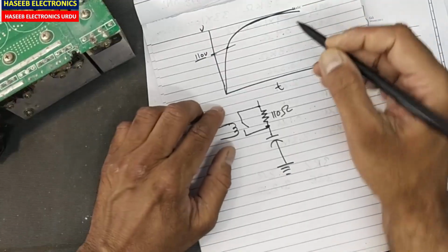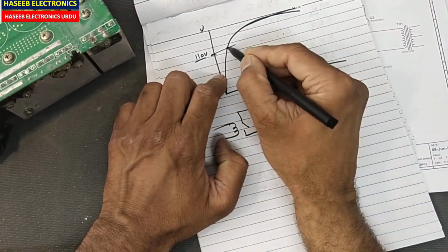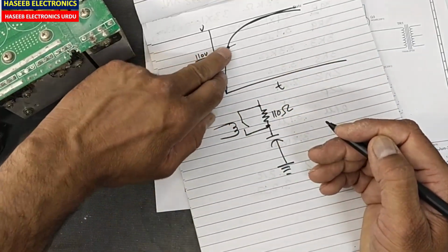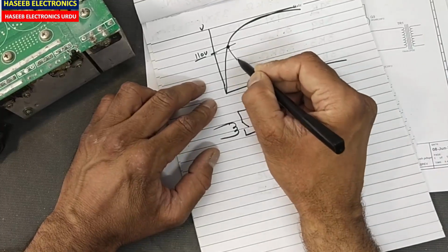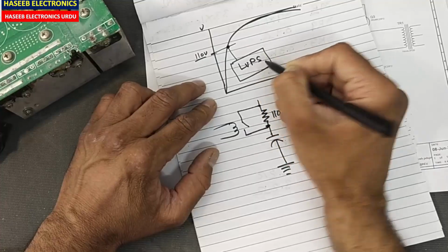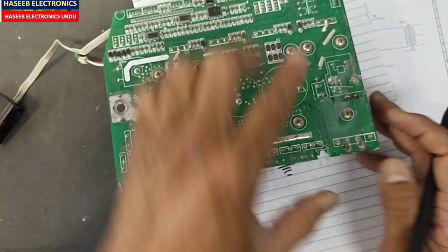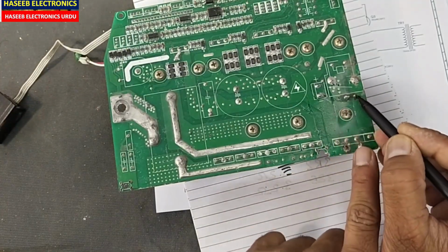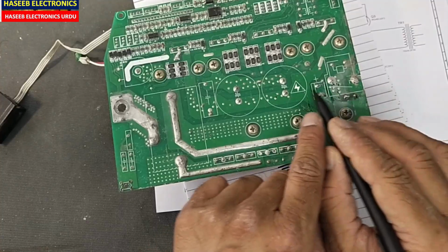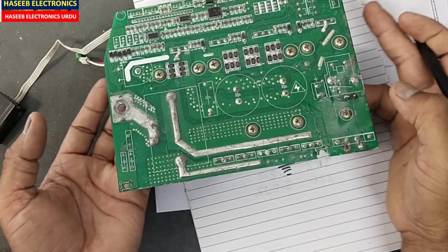Okay, when the voltage reaches this point, we can say 110 volt at this stage, the capacitors are reaching a safe limit. At that time a low voltage power supply that is connected at the same capacitor line, positive voltage after PTC, is connected to this positive terminal from the inside connection of these PCB tracks.